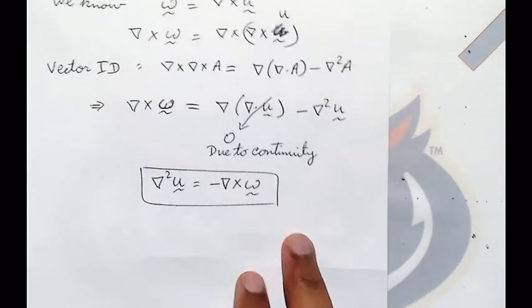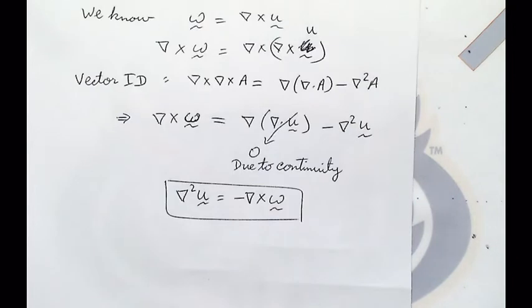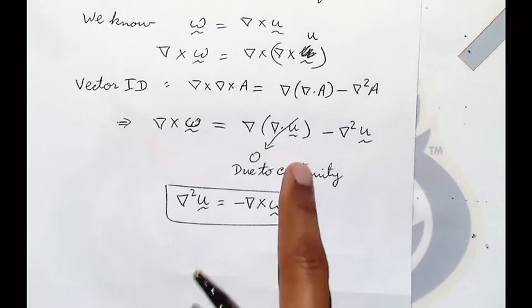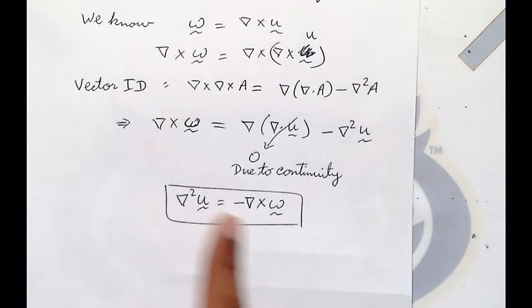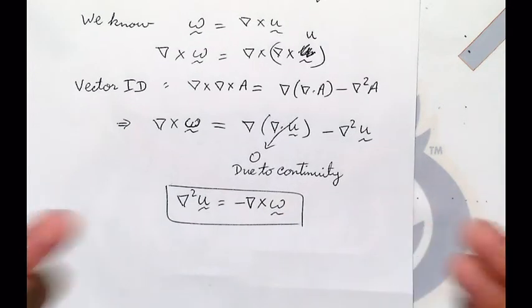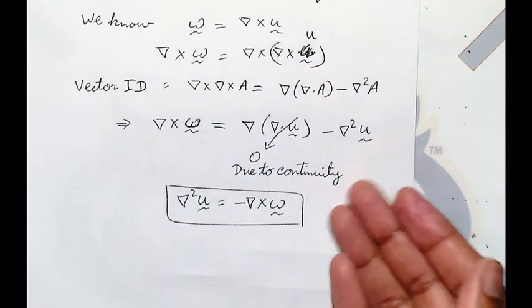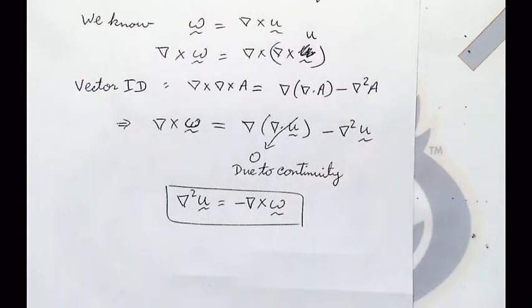Okay? And by now, you should have been screaming at me, we're solving the momentum equation. What about conservation of mass? That is enforced here. When we recover u from the omega field using this formula, we are enforcing the continuity, the divergence of u equals 0.